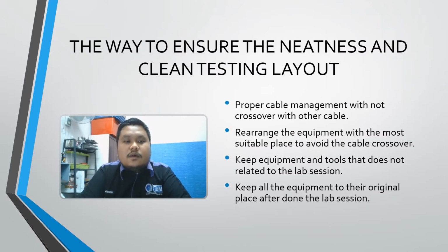Next, I would like to explain the ways to ensure a neat and clean testing layout. First, proper cable management, with no crossover with other cables. This will help to avoid danger that can happen in the lab. Second, rearrange the equipment in the most suitable place to avoid cable crossover.